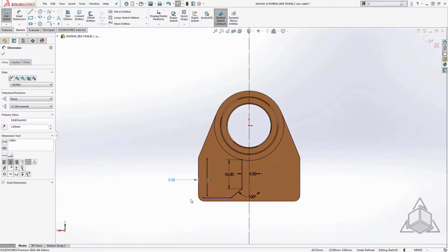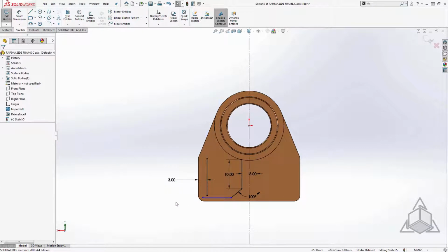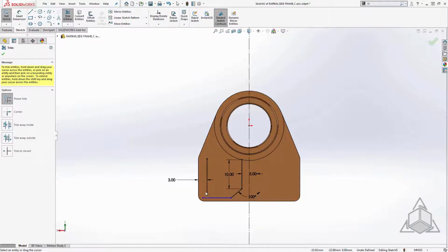Now in cases like this, we may think about attaching these together and then trimming off the rest using the trim tool. What you may not realize is that the trim tool works in both directions. Let's turn on the trim tool again. I use my S key. In this case, I need this to extend, and this I need to be trimmed. If you hold the Shift key on your keyboard, you'll see that Shift will extend. When I release the Shift key, we're back to trim. So you can clean up awkward corners in one operation.